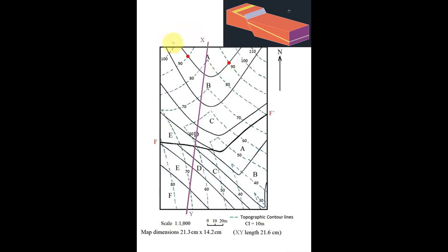So two times it is cutting the same bedding junction. This is what we are looking for, and through these 2 points I can draw a line. This is one strike line that we have drawn. Okay, for the same bedding junction AB, let us say if we have one more, so this 80 is there, it is cutting once here and once here, so we can draw a strike line through that as well.